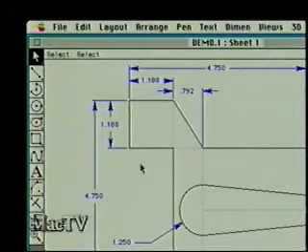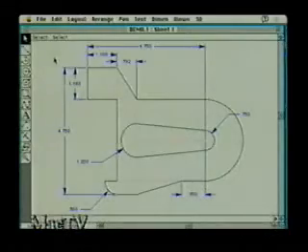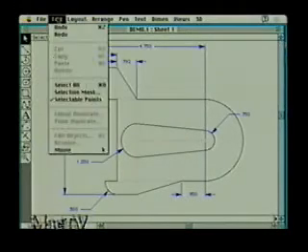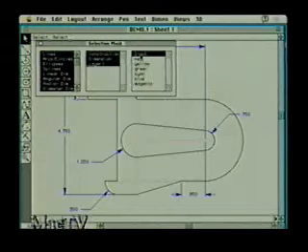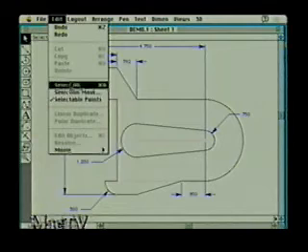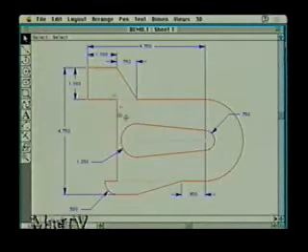So I guess the next thing then, we're working in a 2D plane, but let's take advantage of some of the 3D aspects of this application. Yes, this is one of the unique things about Vellum, how easy it is to move into the 3D world from being comfortable with the 2D world. If I say, give me all the black stuff and ignore everything else, so now when I say select all, it selects all the black things.